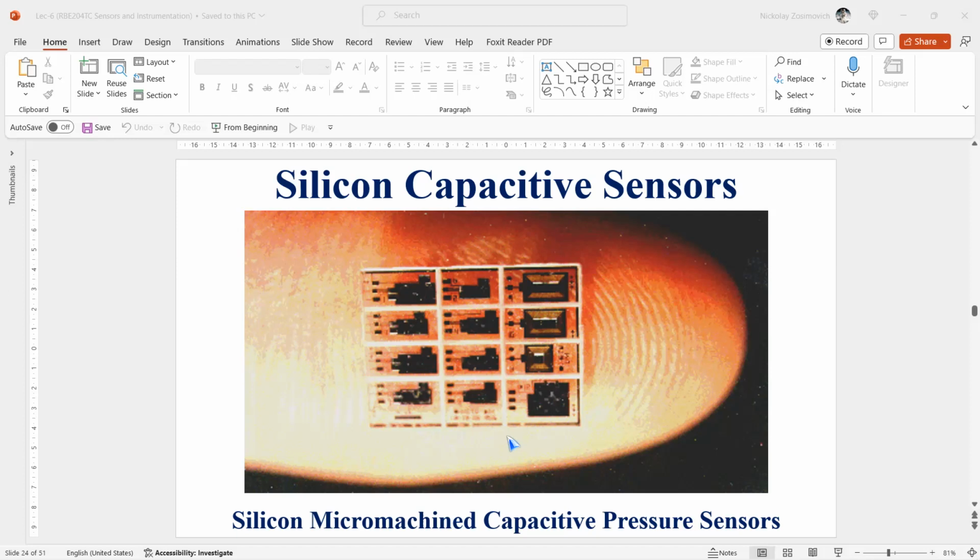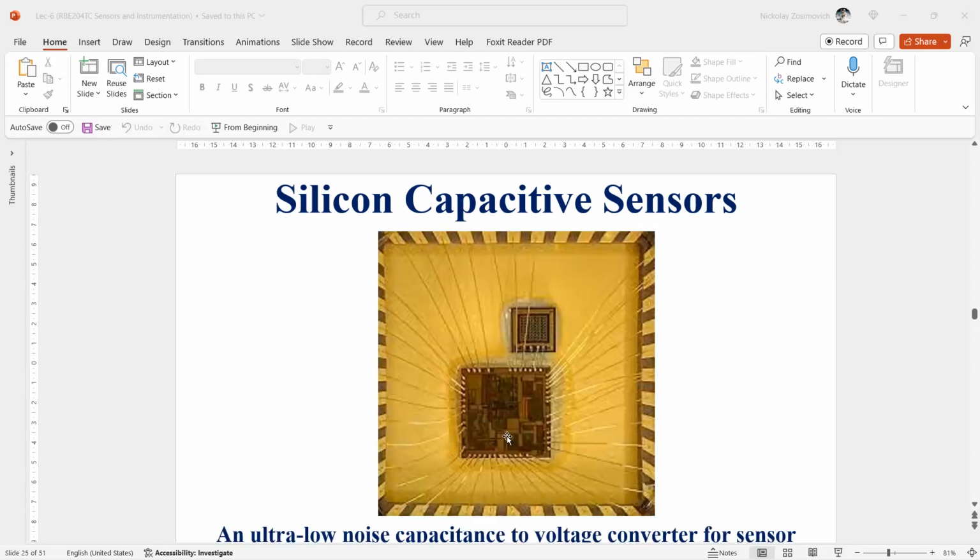Advances in the technology of MEMS, micromachined capacitive sensors, have resulted in the realization of microsensors for other quantities as well, for instance, acceleration. These systems now find widespread application in automotive and other large volume market segments. This technology is highly attractive for accelerometers, rate gyroscopes, and gas pressure sensors, but less for force sensors because of the susceptibility to mechanical damage of the tiny movable parts.